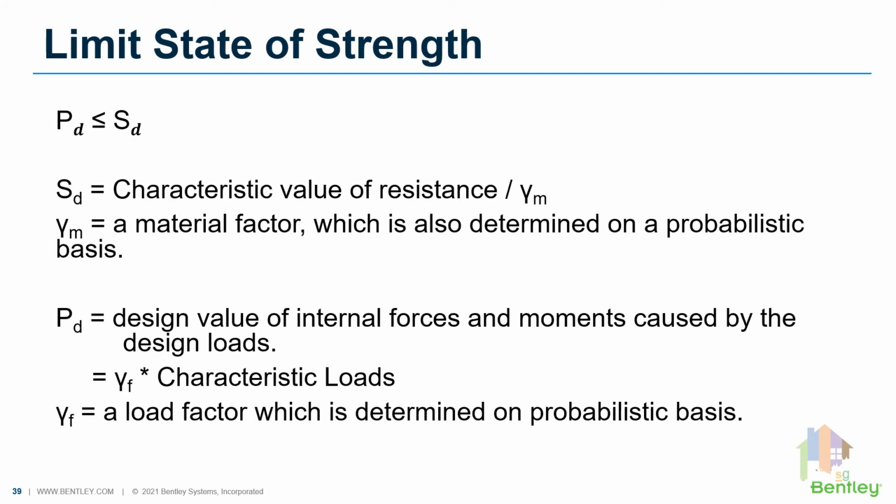Now coming to strength design, the first one is design for axial tension. The basic principle of limit state is to calculate the section capacity and compare that with the actual factored force. Though we consider the ultimate stress value, it is reduced during capacity calculation using material safety factor, which considers the variation of material properties from characteristic value.